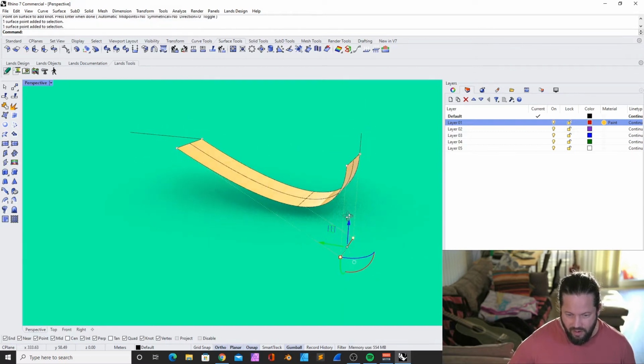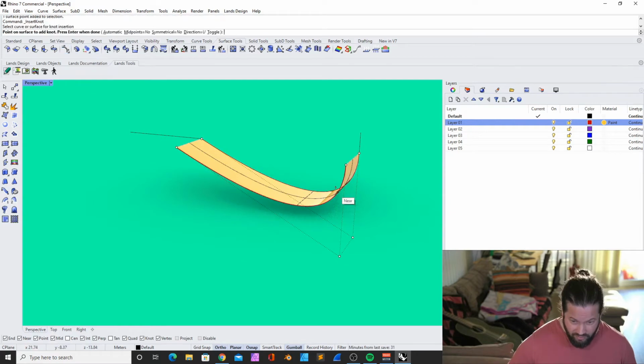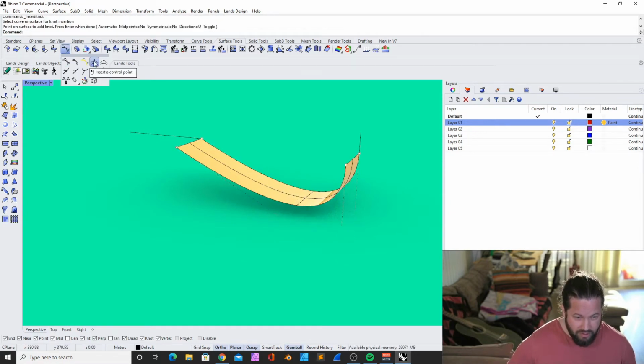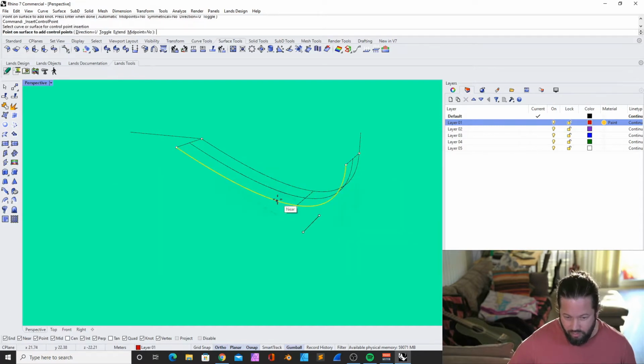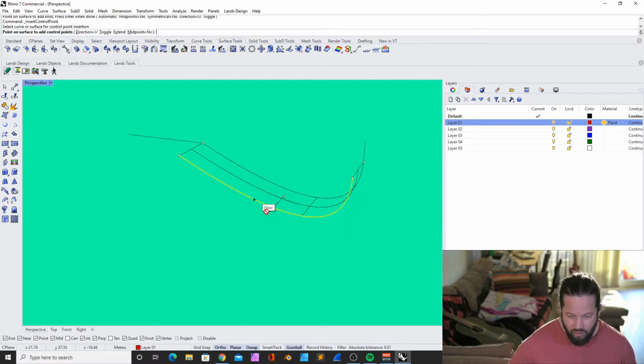So if I want to add one more, there are 2 ways to do that. We either draw the division line and mark this with the knot. It's always along the curve, or with the control points. It depends on what you do on your project. If you need to control your surfaces with control points, then this is the better method.